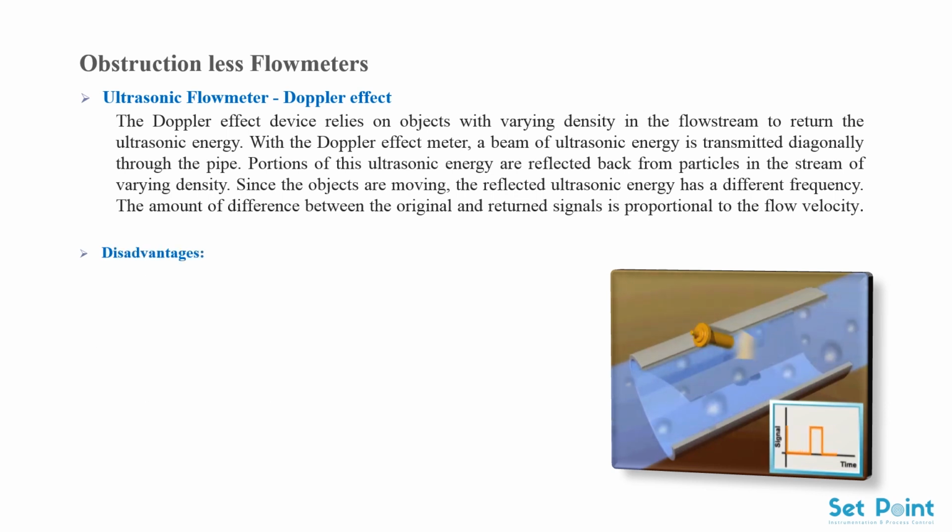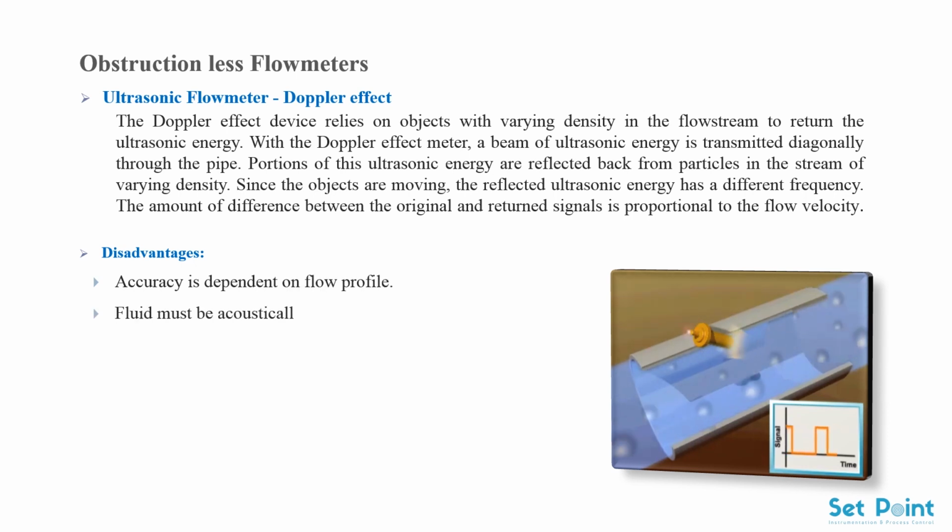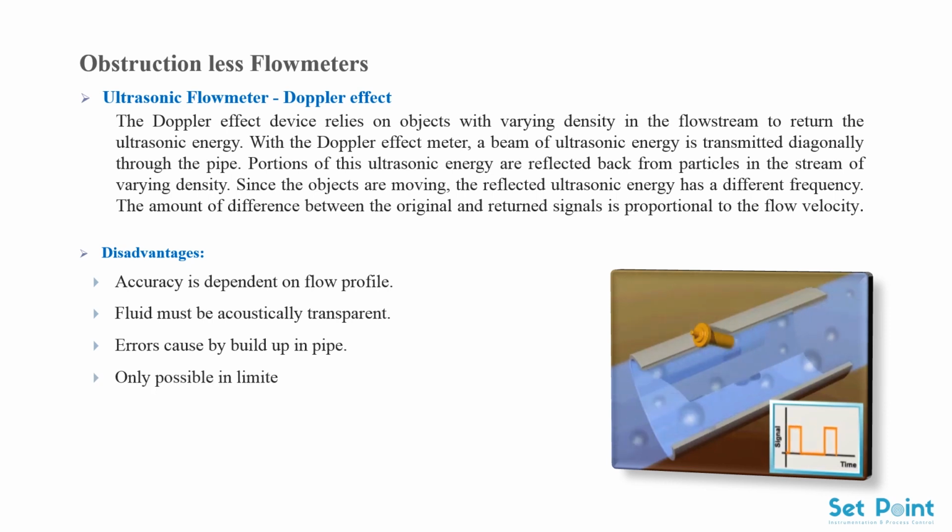Disadvantages. Accuracy is dependent on flow profile. Fluid must be acoustically transparent. Errors caused by buildup in pipe. Only possible in limited applications. Expensive. Pipeline must be full.